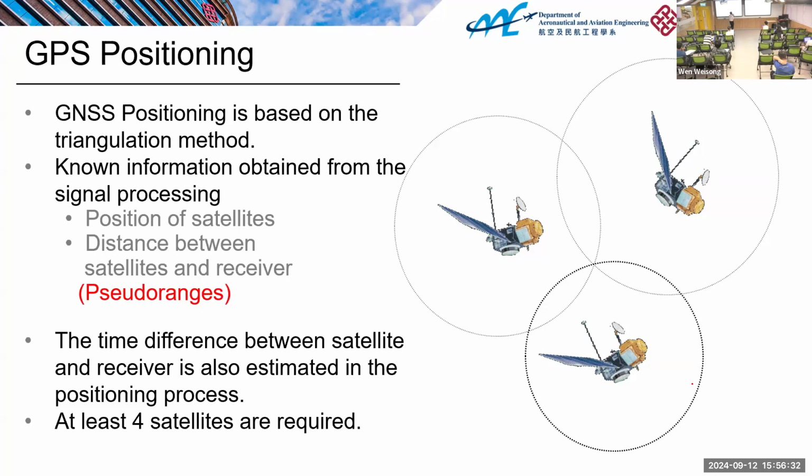It means that different satellite systems have their times aligned, because they all use expensive satellites. But on the user side, I use an Android smartphone, you use an Apple smartphone. Of course, the accuracy of their clocks is different, right? It means there is a clock difference between the satellites and the users. But the good thing is that all of the satellite systems share the clock bias, because they all have very accurate atomic clocks.